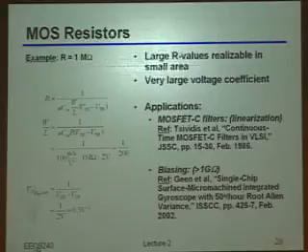The other thing that I will mention here is that, even though transistors can be reasonably useful to get large resistors, the problem with them is that they vary horrendously. Okay? So if before we said that something like a polyresistor was, I don't know, plus minus 20%, something like that, MOS resistors could easily be plus minus 100%, if not even plus minus thousands of percent, depending upon where exactly you bias the thing.